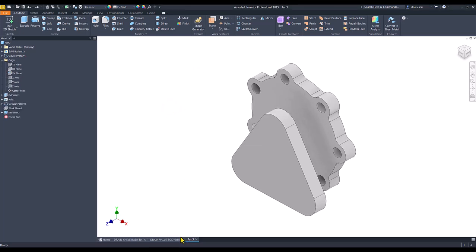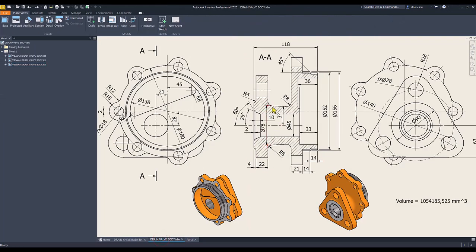Now we have to create this connection between the two features. This is a conical, tronconical shape, 78 with 3 degrees on a side. Be careful, this is the center of the triangle, not this one, the center of the other feature.